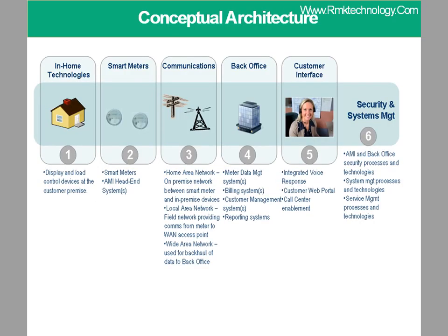This slide depicts the main components involved in smart metering solutions. Smart metering infrastructure comprises smart meters and communication of data from smart meters to head-end systems. From this head-end system data goes to the meter data management system and subsequently to the smart meter app. Other considerations like security and customer are also very vital. There are control devices like air conditioner control etc. that can also be linked to the network. These are called in-home devices. Security is very important for preventing any alien meters or devices being introduced in the network to disrupt the system.